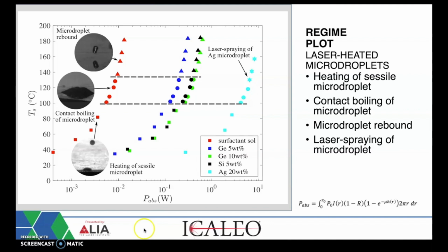And HR is the depth of a liquid interface as a function of the radius. Although the Young's equation is a good approximation of the contact angle at the macro scale, and we could potentially use this for getting HR, it doesn't really predict well experimental results in micro and nanoscales. That's something we noted. Thus, we got HR experimentally, and we approximated basically the interface as a spherical cap, giving